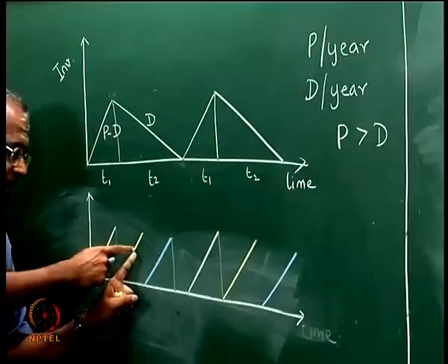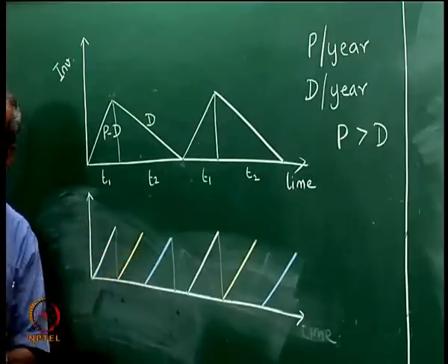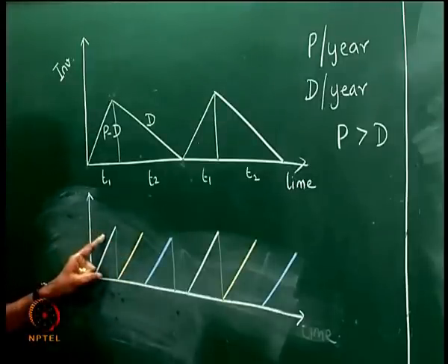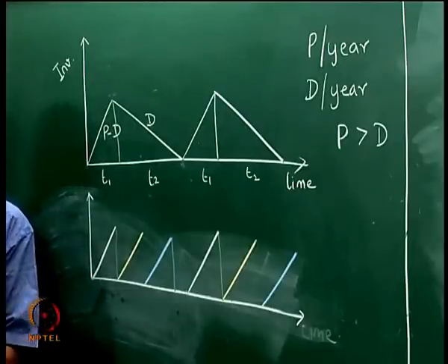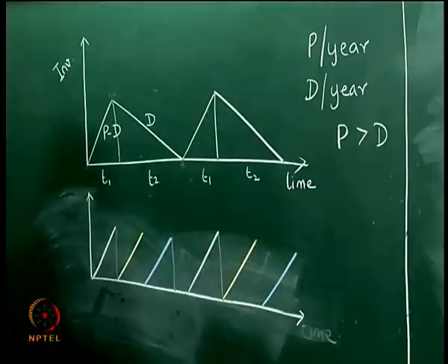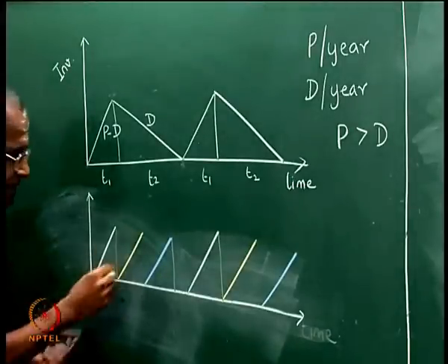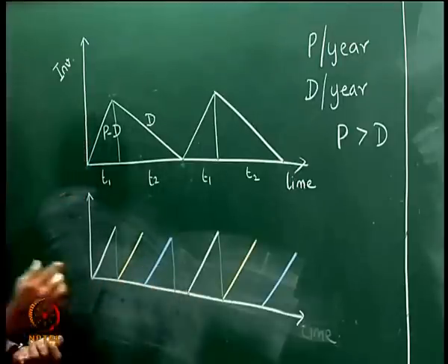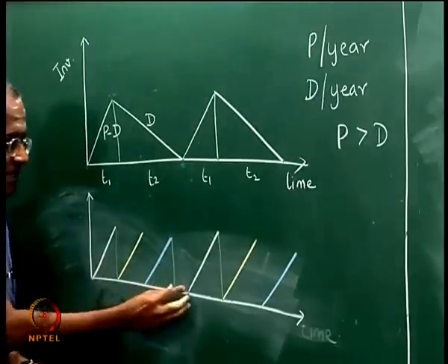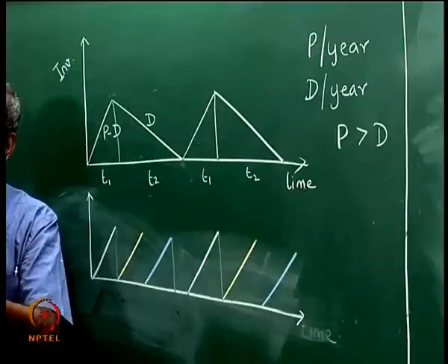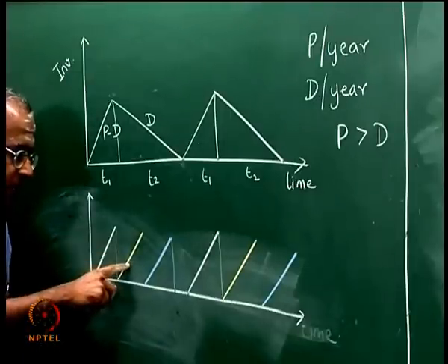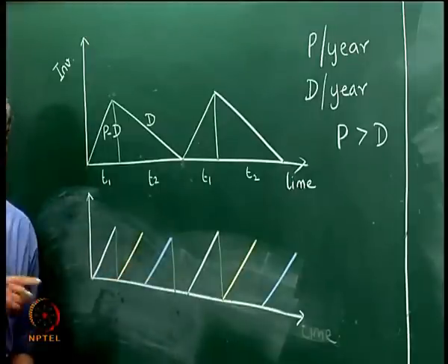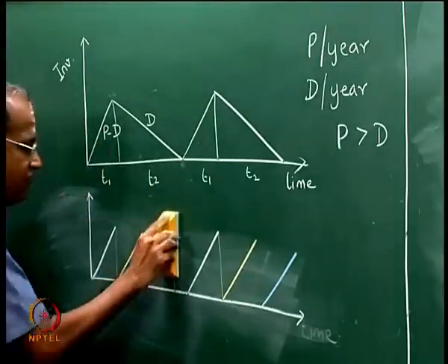When we make a second cycle of the yellow, which is the second item, there will be a cost to change over from white to yellow. But we also have to note that in addition to the changeover cost, there is also a changeover time. So we have to assume now that this gap has to be utilized for this cycle to be effective. This gap should be enough for the time of 3 changeovers, because somewhere we have to change over from white to yellow, yellow to blue and then blue to white,